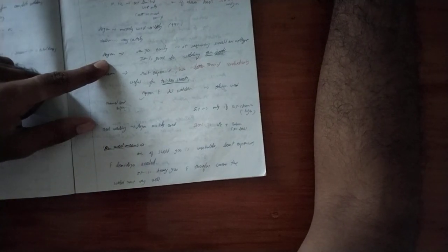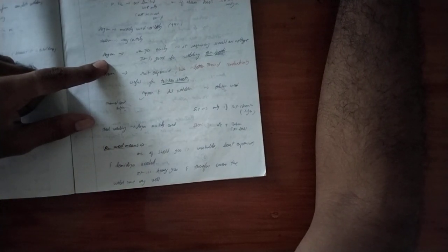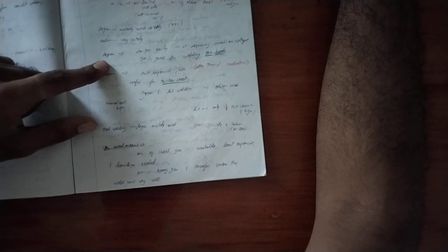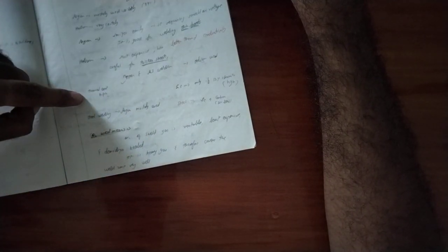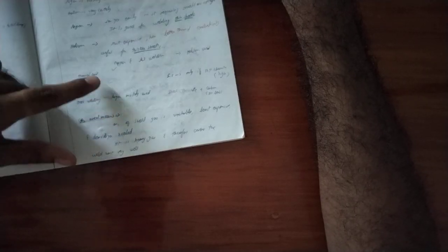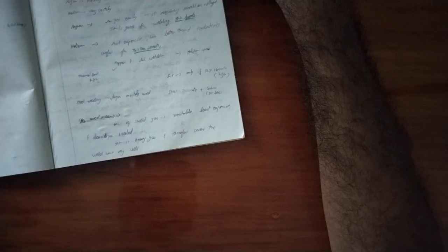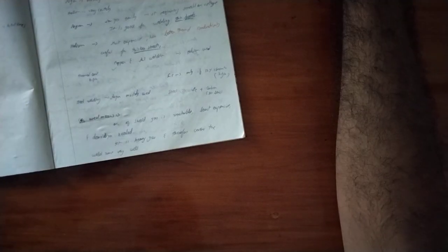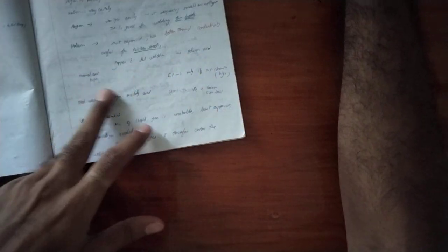Argon's ionization is easy, so it requires only a small voltage. It is used for welding thin sheets. Helium is the most expensive and has better thermal conductivity, so it is used for thicker sheets. For copper and aluminum, helium is used. Helium is also used for stainless steel, which contains 12% chromium.